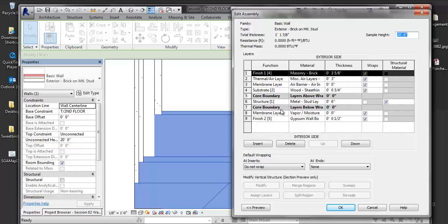I think you have to consider what drawings you see later in drywall. In a lot of cases, I recommend modeling to things that show up on quarter inch drawings, quarter inch elevation, quarter inch plan, what kind of detail shows up there. You would never see layers of finish necessarily. And if you wanted that detail represented at 3 inch, do it as a drafting view.